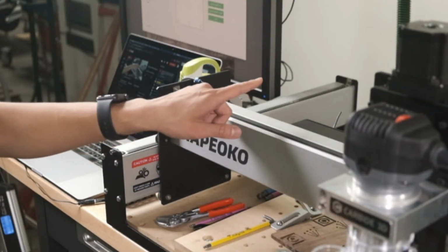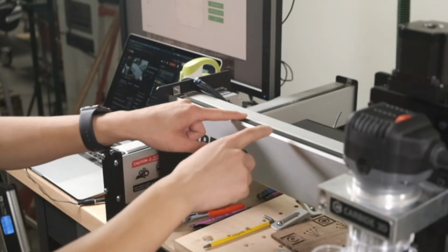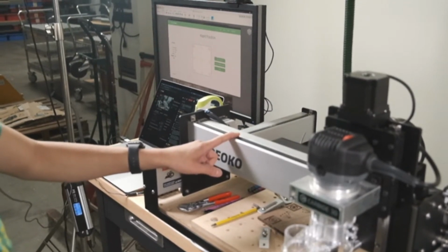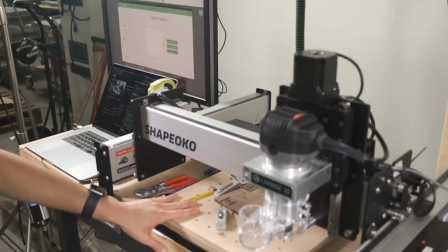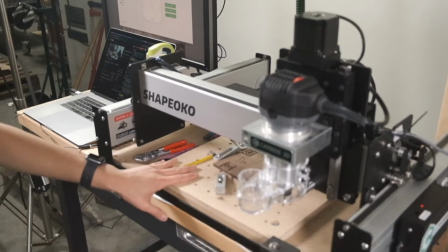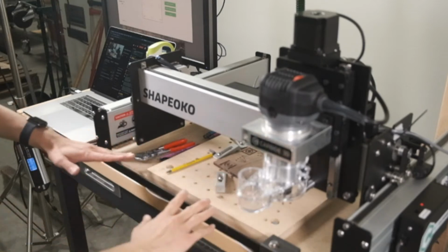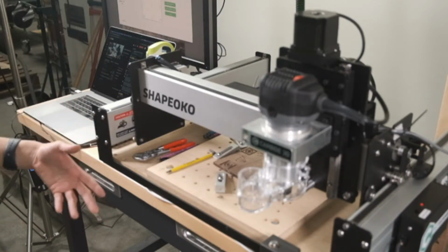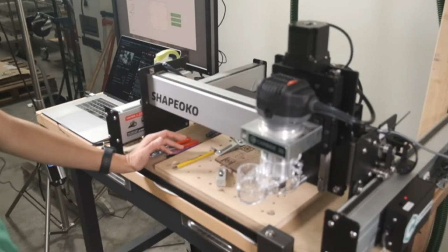I would say check seasonally with large temperature shifts, because aluminum and the belts are going to expand and contract at different rates. Seasonally is also a good time to maybe surface your wasteboard, because as the MDF expands and contracts through humidity changes, it might cause the frame to bow or sag in different ways. So big temperature shifts, seasonal changes, humidity shifts. If you're in a climate-controlled place, unless you have a really bad machine crash, you probably shouldn't need to worry about